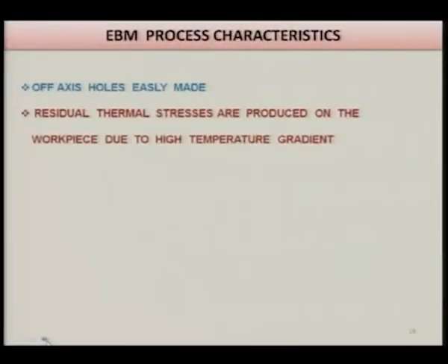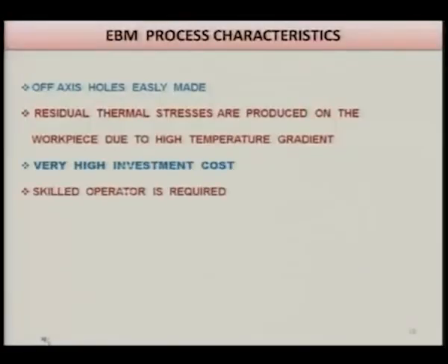Residual thermal stresses are produced on the workpiece due to high temperature gradient. This is very important because this is a thermal process. Material is being removed by melting and vaporization, and there is always very high temperature gradient, and because of this you are always left with the machined component having thermal residual stresses, and in many cases you need to anneal such pieces or remove those thermal residual stresses before putting them into the devices. Very high investment cost, and it requires skilled operators.